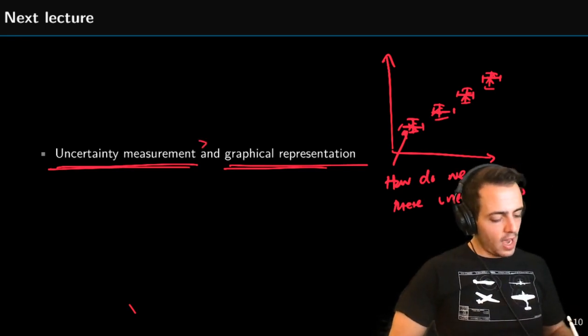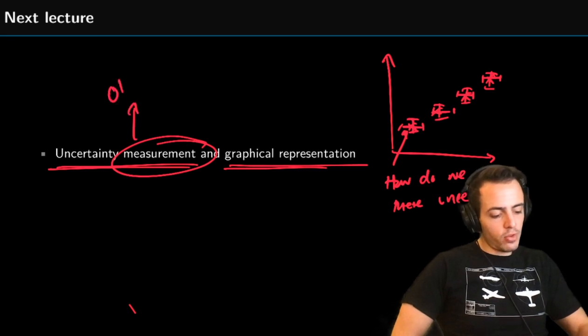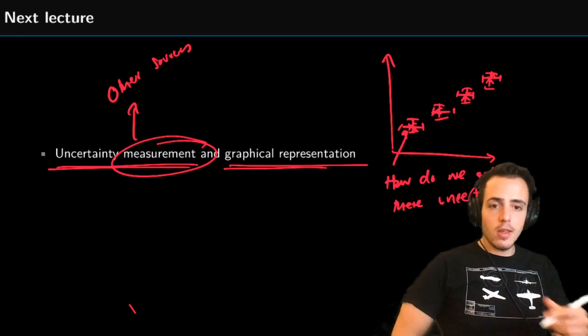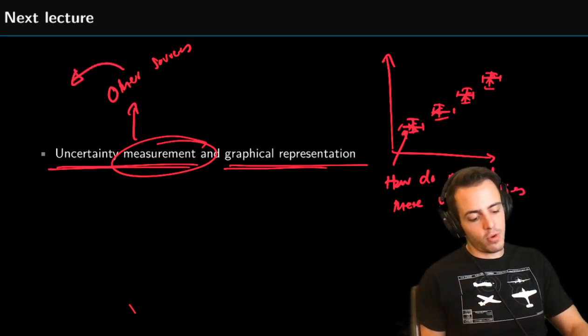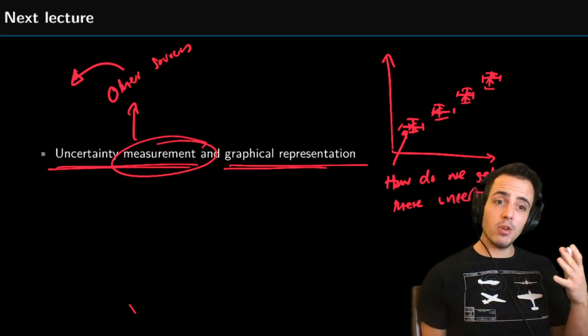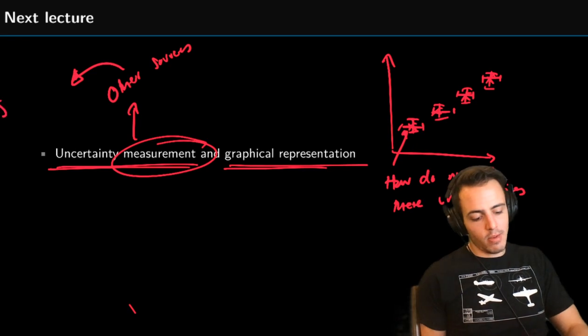So how do we get those uncertainties? It's not just a case of measuring the uncertainty in data we've taken. We've got to think about other sources. So other sources of uncertainty that we can have, we've spoken a little bit about them before. If we're using an ADC, an analog to digital converter, then we've got a sensitivity.